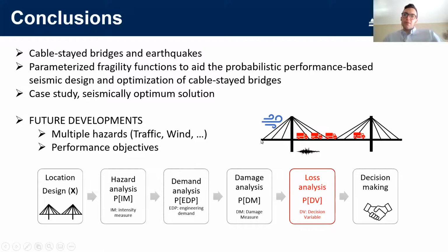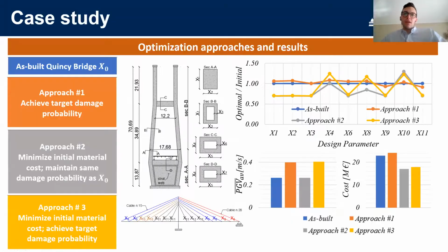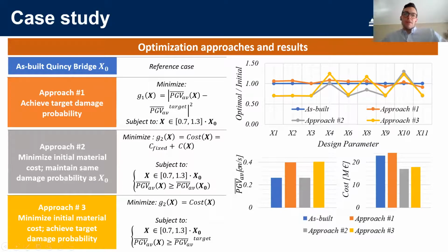So for example, for one time history, I will consider the traffic load just distributed on the first part. And then for the next one, for example, it might be in the medium right one, or in the extreme right span. But about how to include that in the process, I'm planning to include that as a boundary condition. So for example, by controlling the peak displacement due to traffic load coming from the design configuration we are considering.